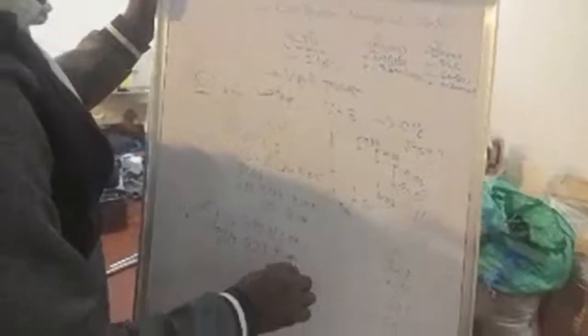Now let's say this: N40, G71, U1, R1, then our N41, and N41 can be G71. This is a syntax for Siemens G71. You can use P, let's say our P is 42, Q is 45.